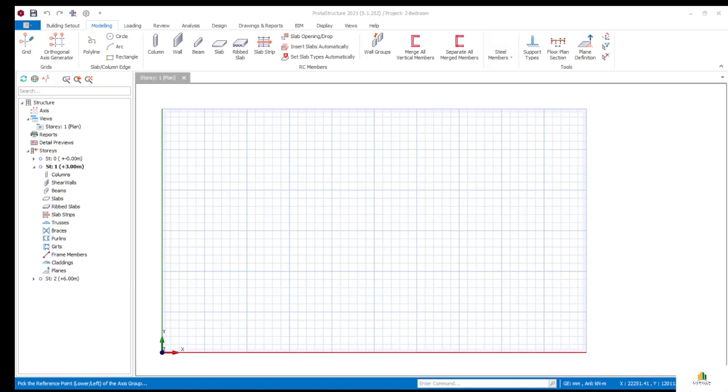But if you have, let's say, 3 interval axes that have similar length, let's say 2,000 asterisk 3, then you can get that without repeating 2,000, 2,000, 2,000. I'll get it so that you can work fast. Let's also type 4,500, right? And comma, let's type another 3,000. Okay, yeah. Then let's move on to the direction 2.